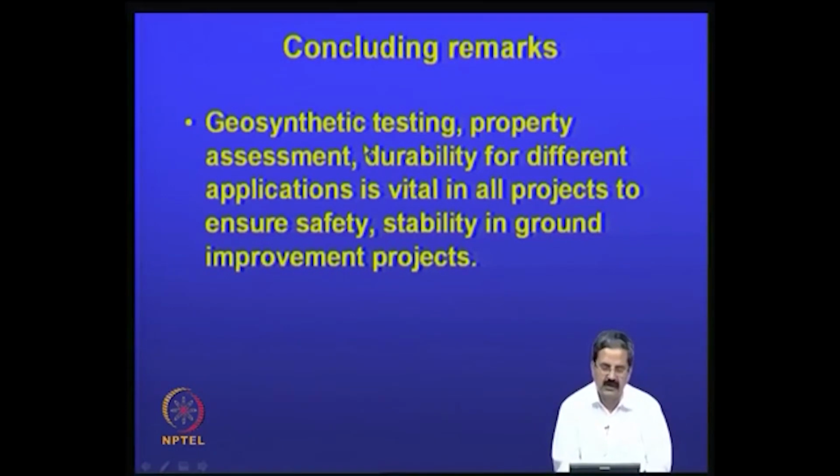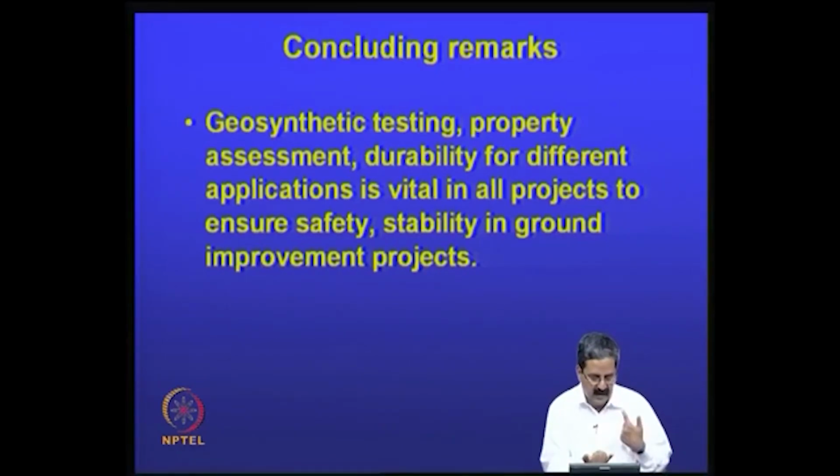What I would like to mention is that the geosynthetic materials, you are using them for mechanical properties and then hydraulic functions. So for example, we know that the functions of the geosynthetic material are reinforcement, filtration, drainage, then moisture barrier, separation. There are so many properties that we studied as their functions. One should really understand the application and also get that property properly.